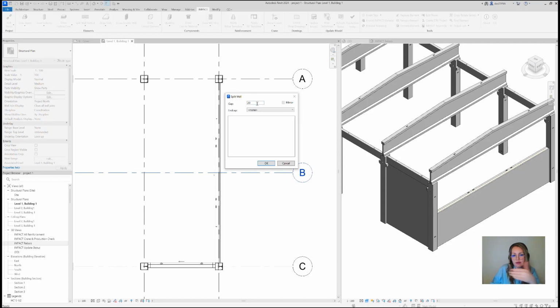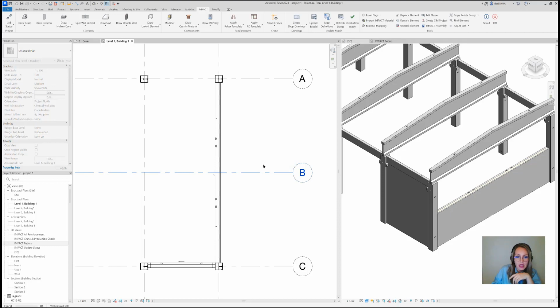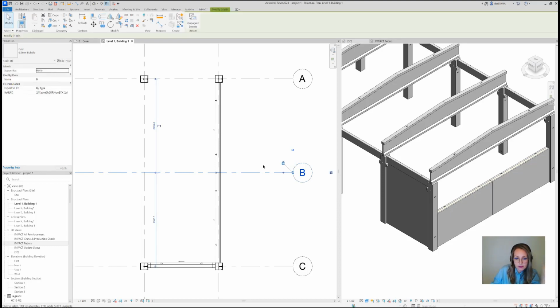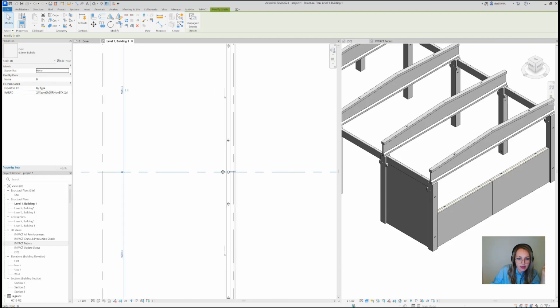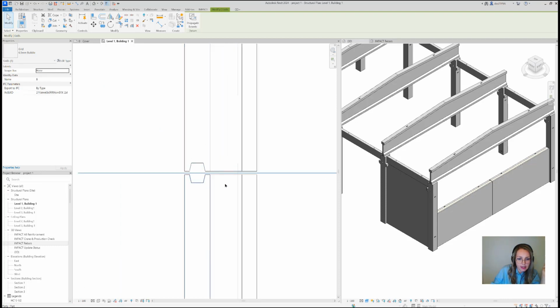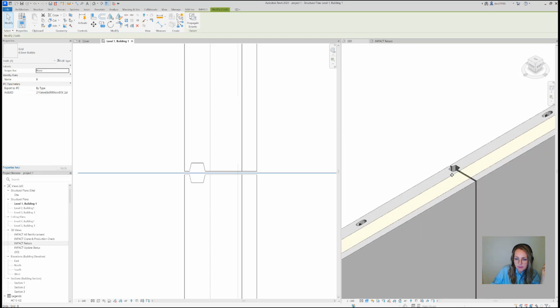Here you can insert the gap between those walls. Let's say we take it as a 16, and pay attention that while doing it, you can actually add an end geometry automatically to these two ends of the wall. So all those in caps that I have in the database, you can go and already use now. Here it is. I split the wall, inserted the gap, and I have my end geometry defined. You can see it in here.